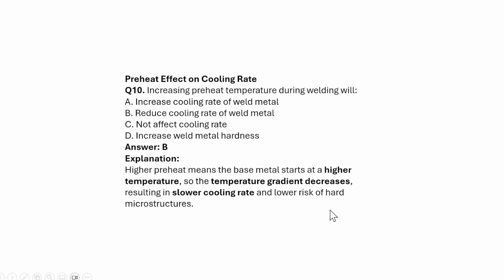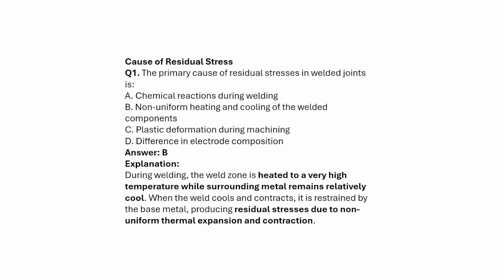If we increase the preheat temperature during the weld, what will be the effect? Increase the cooling rate? I think it is also already seen. So it reduces the cooling rate. So the answer will be B.